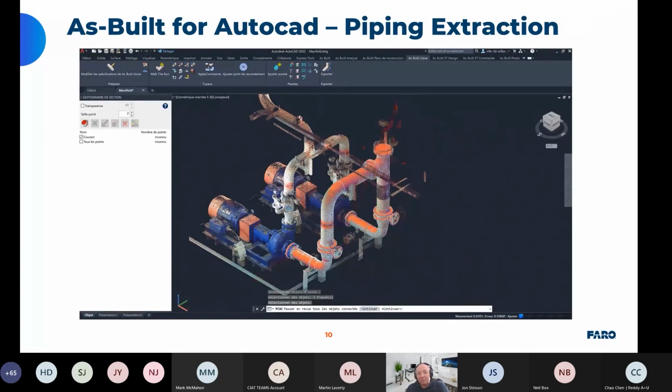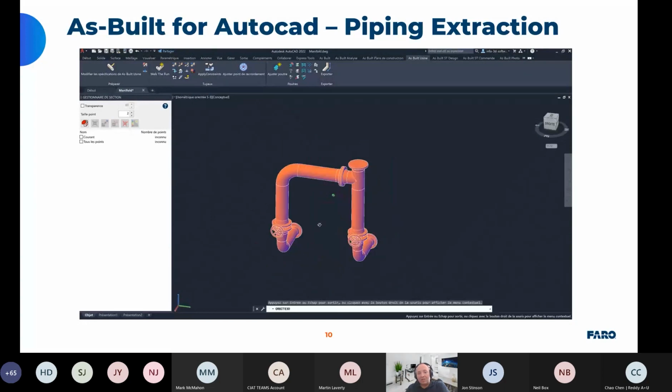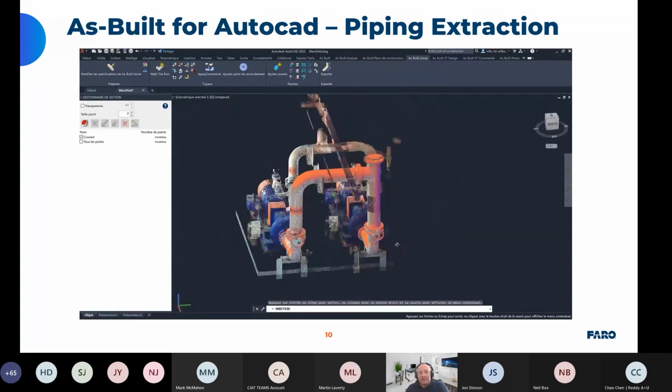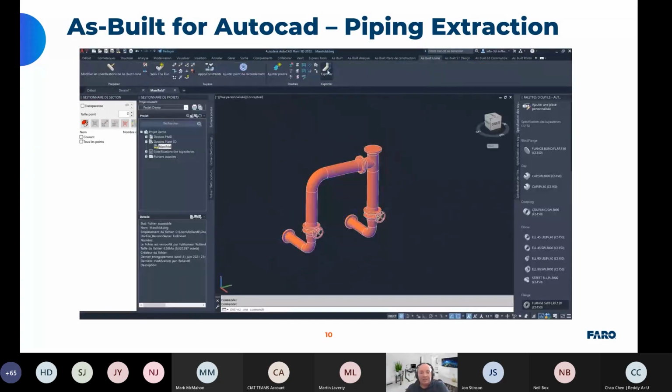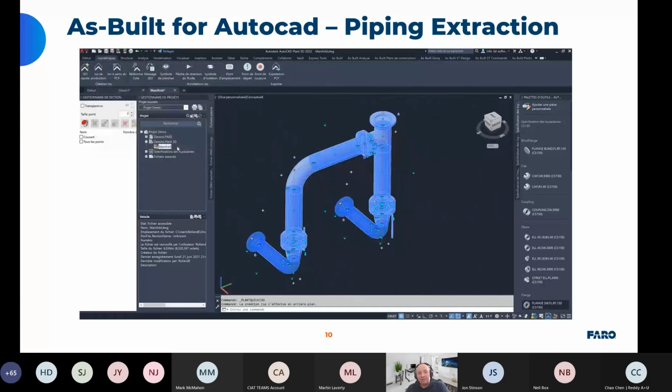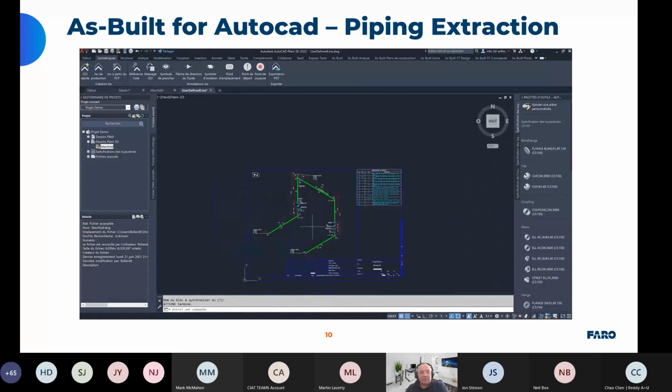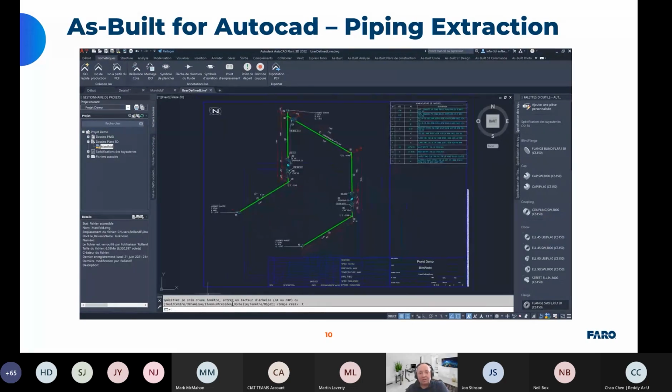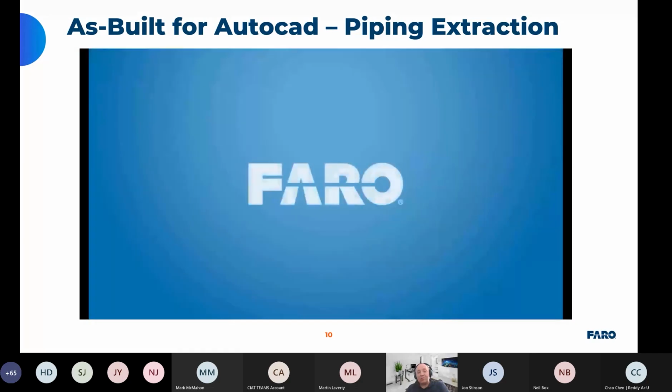So you see, very quickly I can finish the inlet and outlet of each pipe. The only thing I have to do to conclude the pipe is to constrain the piping generated with the point clouds, so we try to be as close to reality as possible. And in a few minutes, I did these pump inlets. After, I will extract the data, for example into Plant 3D, to be able in a few seconds to generate some isometrics directly inside Plant 3D. I just have to select my drawings and I can generate my isometrics very quickly. When it's done, I've got the 2D drawings with my bill of materials, all my dimensions, and all the parts that I have extracted from the point clouds are here. It's very quick and straightforward. Everything I show you is from out-of-the-box data.